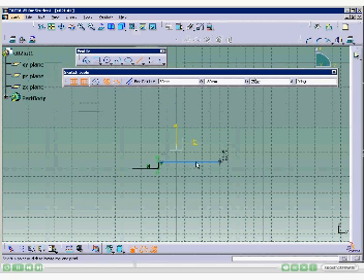Select the end point of the vertical line as the start point of the second horizontal line. Enter 75 in the Edit box of the Sketch Tools toolbar. Move the cursor horizontally toward the right and click when a horizontal line is displayed. Select the end point of the second horizontal line as the start point of the second vertical line, and move the cursor vertically downward. Click when the length of the line in the Edit box shows a value of 8 mm, or enter 8 mm directly in the Edit box of the Sketch Tools toolbar.